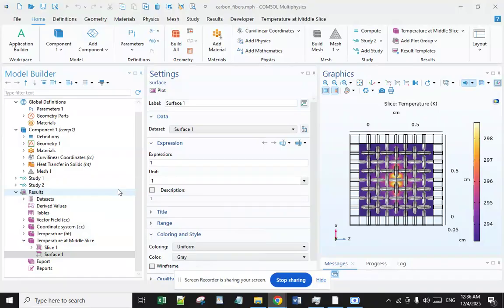This is because the carbon fibers themselves provide a continuous path for heat, while the non-conductive polymer matrix and the gaps between fibers hinder heat transfer in the through-thickness direction. The overall thermal conductivity is also affected by factors like fiber volume fraction, yarn tightness, and the specific weaving pattern.